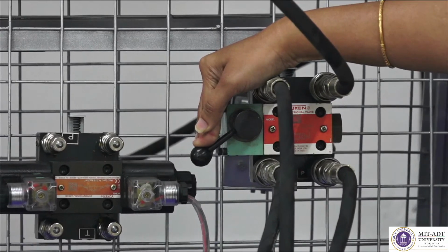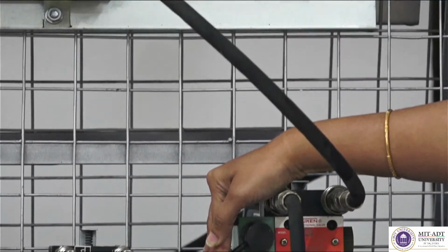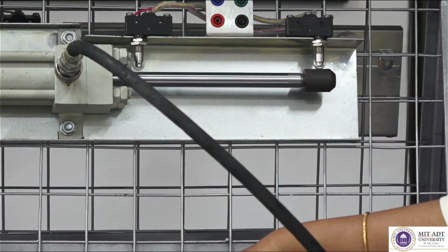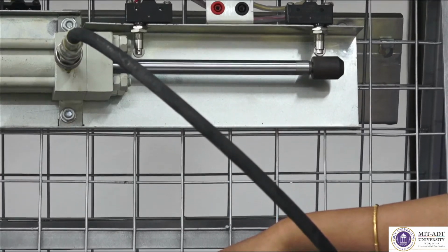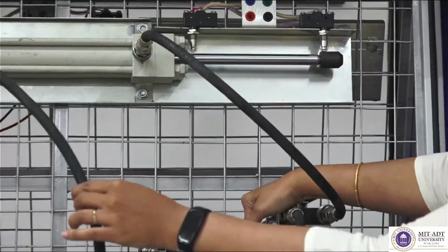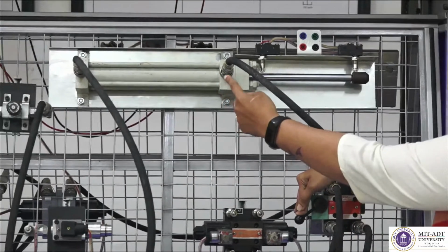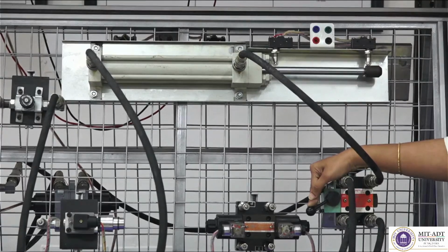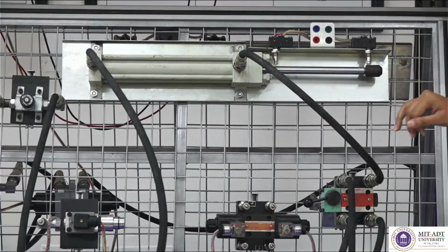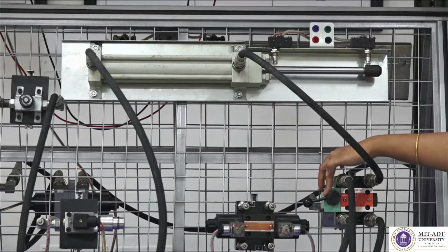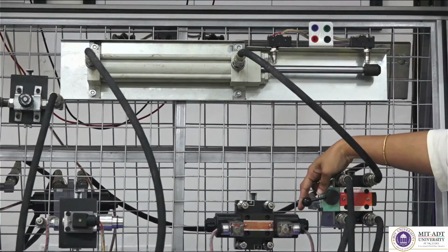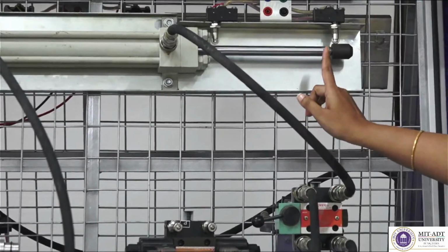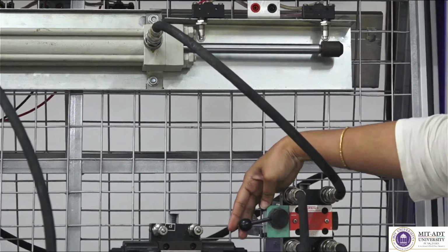So, what you can see over here is the rod end part of your double acting cylinder is getting extended. So, pressurized fluid is going to enter into this side of the port. So, there is a piston inside a cylinder which would be moved in an outside direction. So, again when I am releasing this lever, it is coming back towards its middle position, which is called the hold position. So, whatever position has been acquired by this double acting cylinder has been kept on hold for that particular period of time.